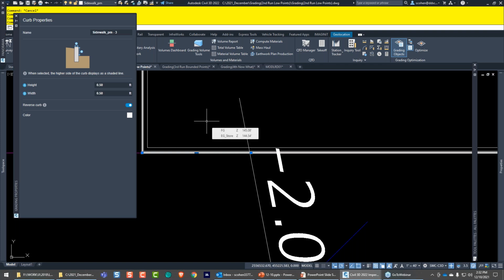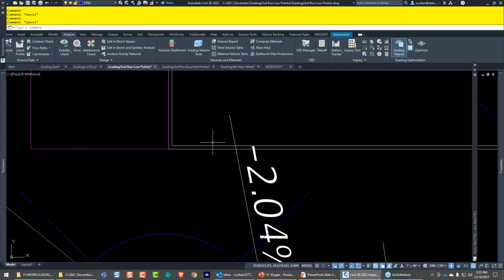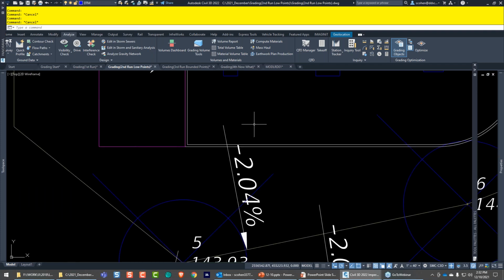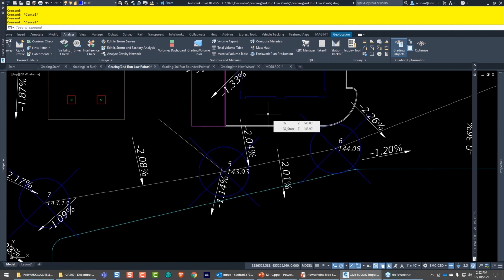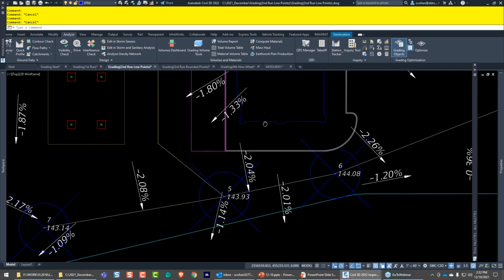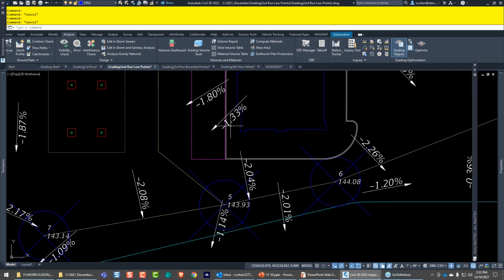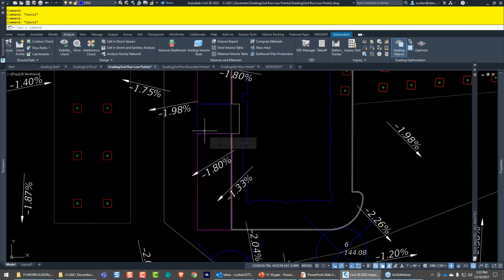It was just something to basically show it, to actually have the sidewalk and all that kind of stuff work. Okay, I found that it wouldn't work with just the curb and gutter. It was creating all kinds of really deep slopes because there was no zone to lock in that 1.5% cross slope that we need across the sidewalk. So that's what I had to do. I had to lock it in that way. That's how you have to think about it. You start big and then get granular as you need to, to get the zones and the grading you want it to do.